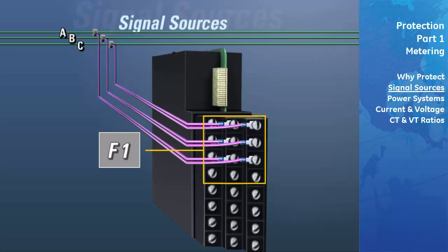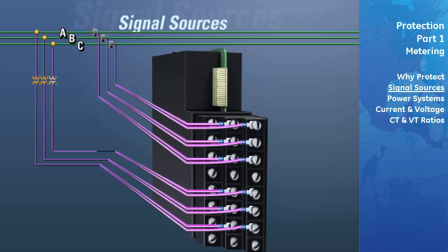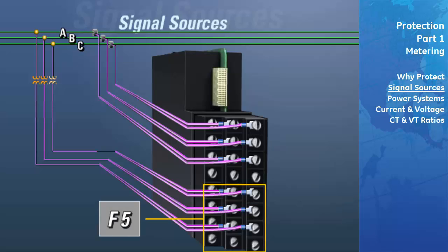If a circuit is connected to the second set of inputs on the DSP in the F slot, phase A will be located in row 5. Therefore, the name given to that particular group would be F5. All DSPs installed will follow this naming convention.